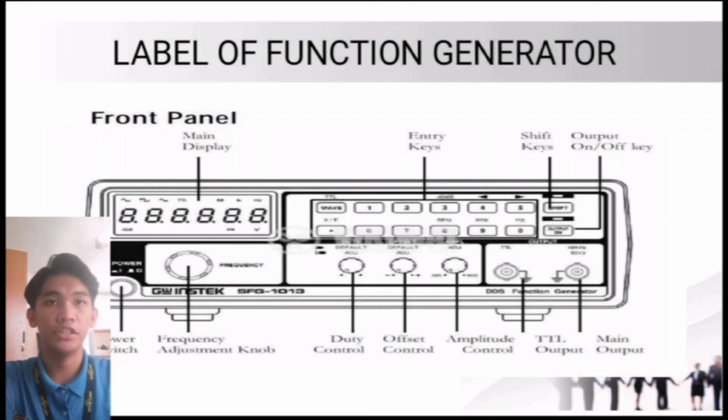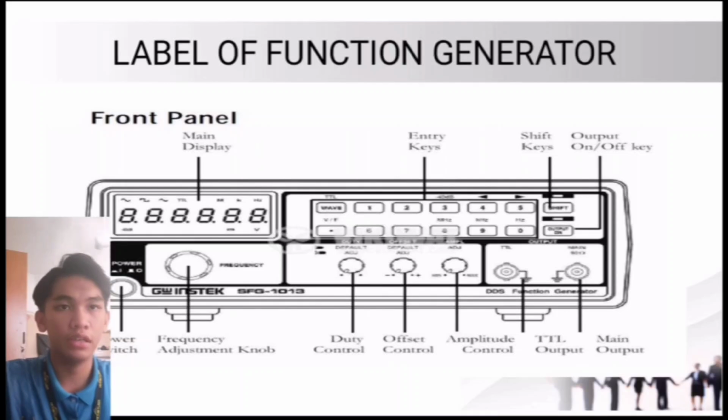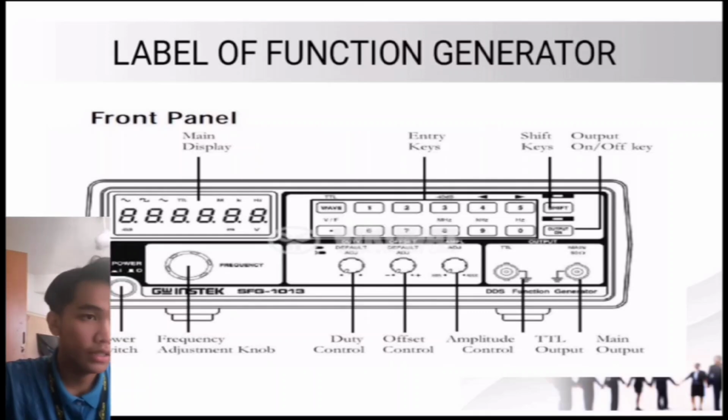So we can see here the layout of the function generator front panel, such as the main display, entry key, shift key, output on-off key, power switch, frequency adjustment knob, duty control, offset control, amplitude control, TTL output, and main output.